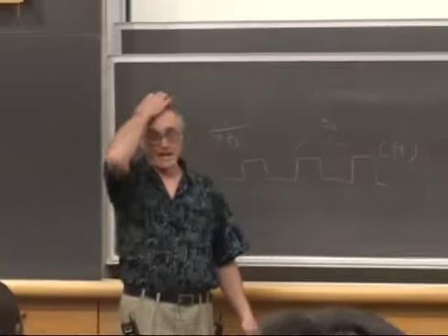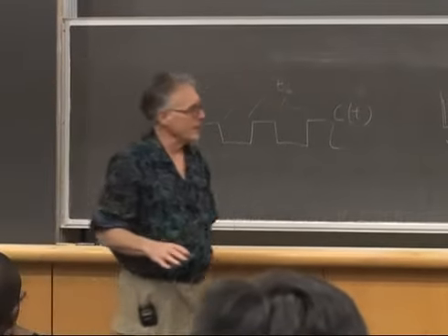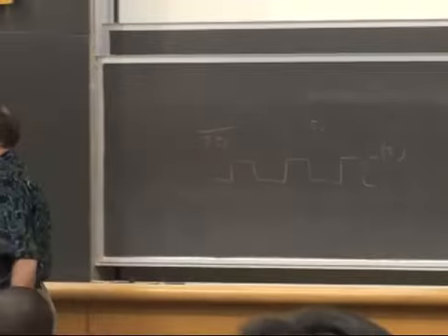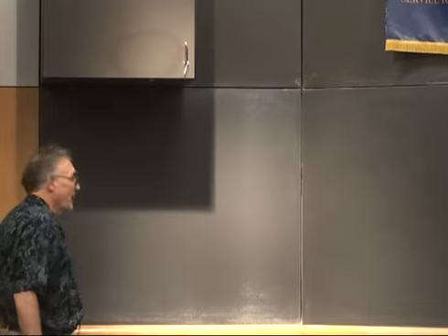One of the errors I've seen a lot today, and it really surprised me, is that my output compare code initialized two separate output compare units, and it appears as if one of them is correct to use for PWM, one is not correct to use for PWM. It appears that people rolled the dice and chose one.